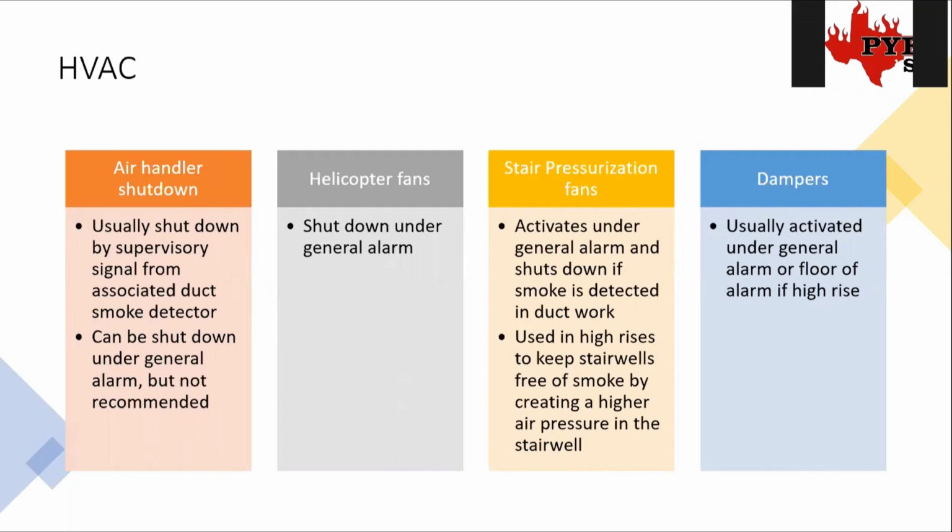We just use a relay on these. We shut them down under general alarm. When we did the relay lesson, I talked about a couple ways to wire up where you have an addressable relay that can't handle high current circuits, and we can use an MR101 so that our addressable relay trips the MR101, which is a much stronger relay.